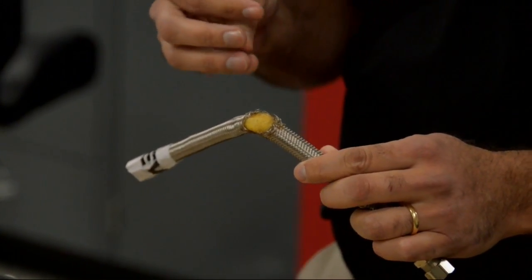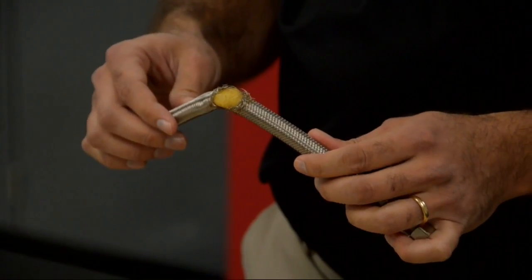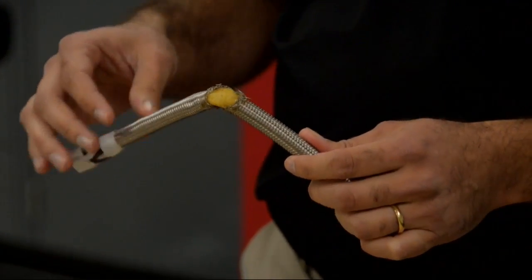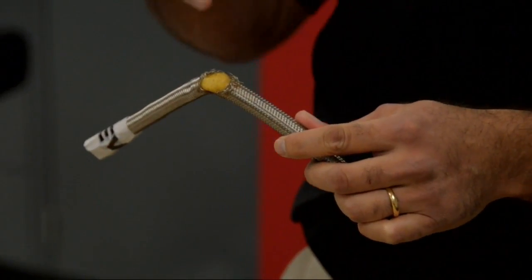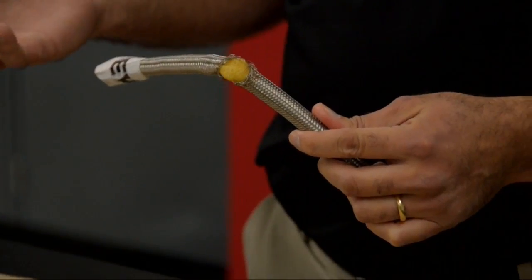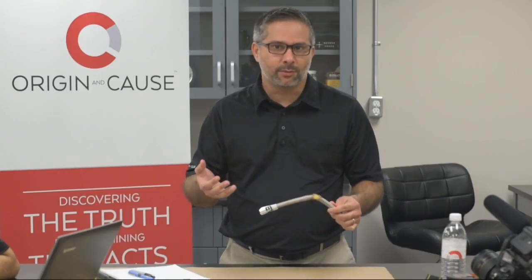And in terms of the life expectancy of these parts, most plumbing components should last at least 50 years. So the fact that they're failing at 2-3 years, well, that's early, but they also fail at 7, 10, 12 years, and I get these questions a lot. So this component failed after 12 years. Does that mean the component was old or worn out? No, not really. They shouldn't fail at that age, and they shouldn't fail in a way that is unexpected. If you see a lot of rust on them, if you can see them degraded, of course it's a maintenance issue. But most of these components we see don't show any signs of degradation or damage before they fail. So it's a tough one.